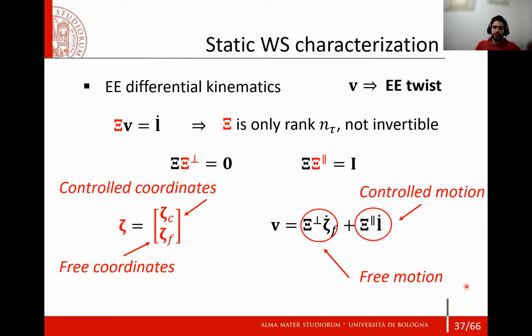To study this phenomenon, we first needed to establish which robot variables might affect end effector pose change. Differential kinematics shows us that since the robot Jacobian is not full rank, meaning its rank is less than the number of degrees of freedom, an infinity of rigid body motions may happen for a given cable length velocity or cable length instantaneous change.